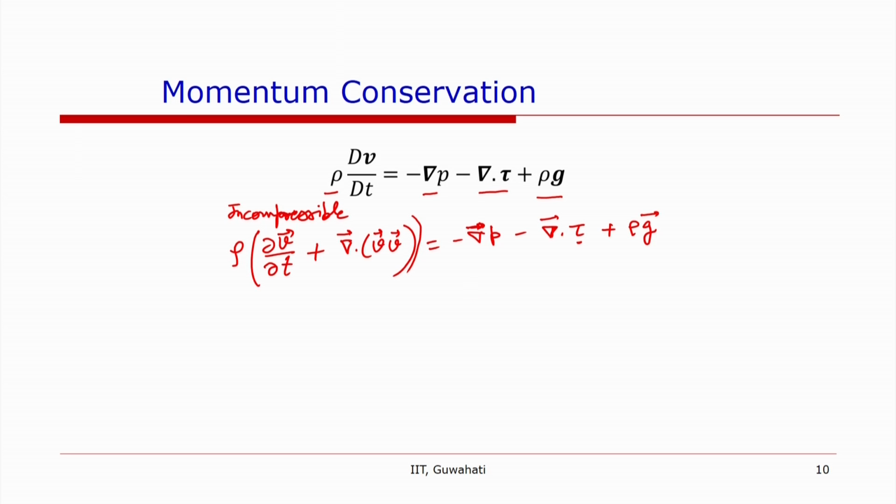If we look at pressure, one unknown, and velocity as a vector, so two unknowns, and we have two equations. One is the mass conservation equation and another is the momentum conservation equation. So, in principle, using these conservation equations and the appropriate boundary conditions, one can solve for the fluids. But we have a new term here, which is tau, shear stress. So, before we solve these equations, we need to close tau, or we need to find a relationship for tau